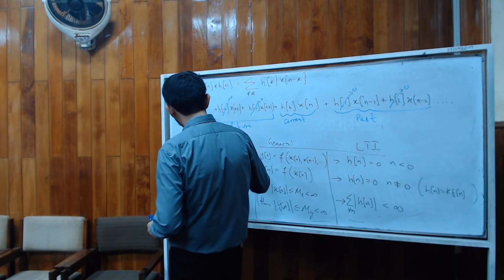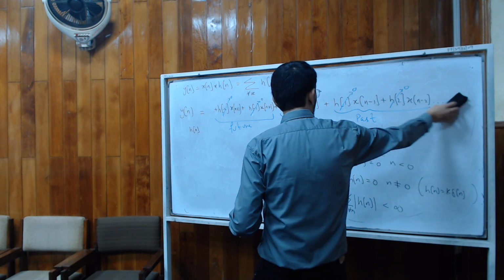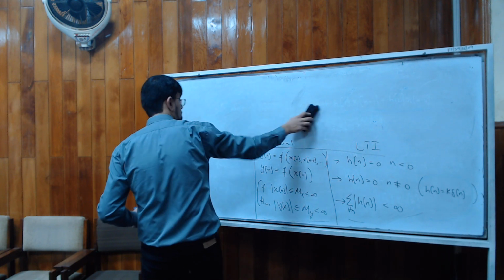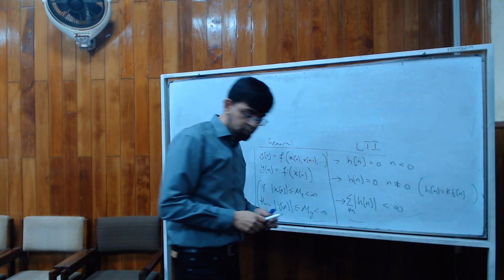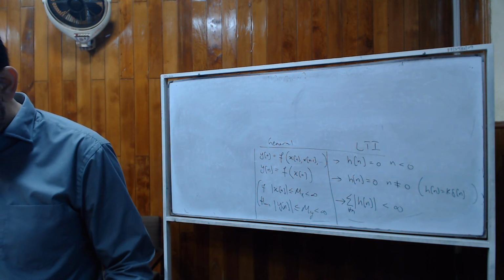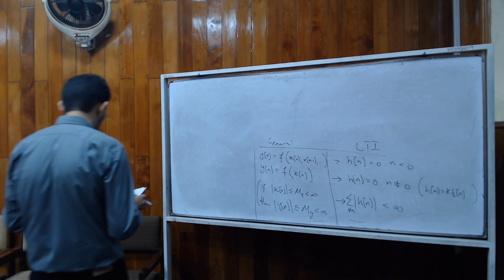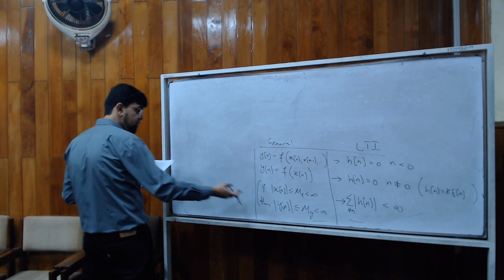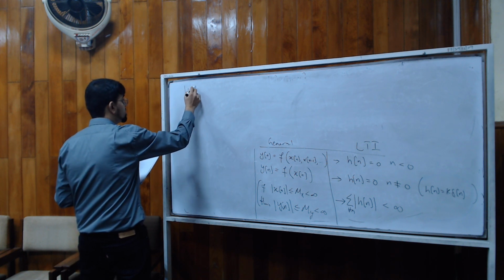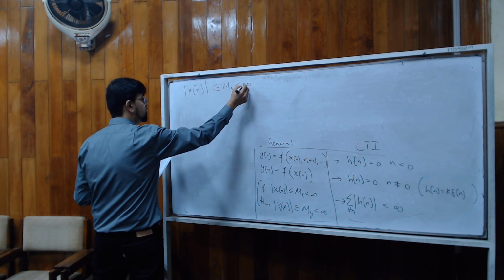We will do more examples for that, but let's do the last one, which had to do with stability. What would be the test for stability? I've already written that there, but let's derive that test. It is quite an interesting thing. As before, let's start with the general test. Let's say that we send in a bounded input. So we assume that the input is bounded: |x[n]| is less than or equal to Mx, which is less than infinity.